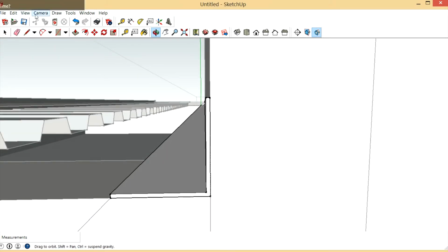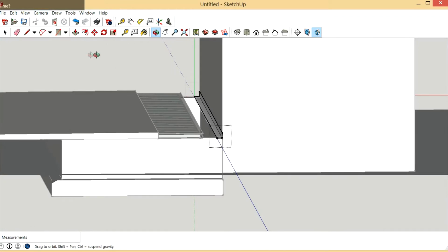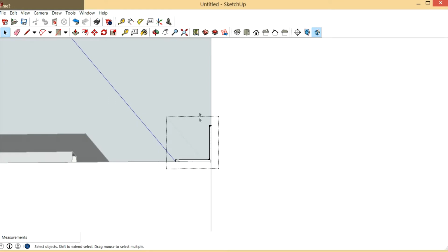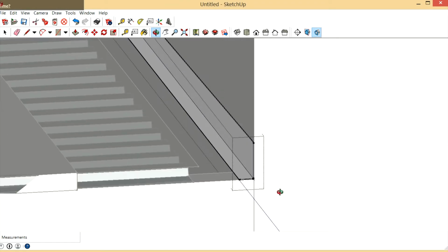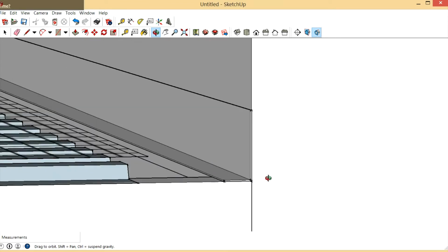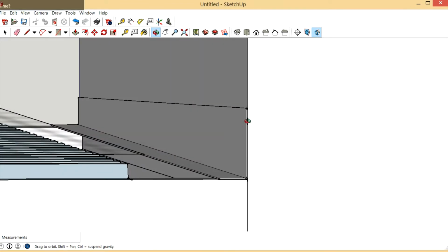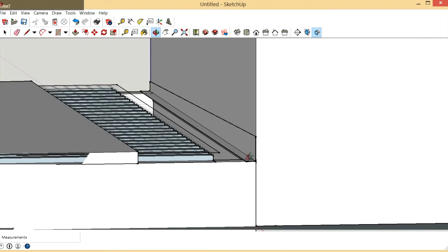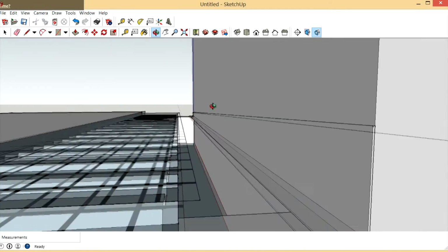What I'm going to do is go back to this parallel projection, so that when I'm looking at it, I don't have to worry about that. So I'm going to raise this up 6 inches, like that. So now my flashing is good, it doesn't necessarily have to be this tall. What I'm trying to get you to do is get it up 3 or 4 inches above the concrete, and I'll show you why in a second. So I'm going to put this back on perspective because it's freaking me out.